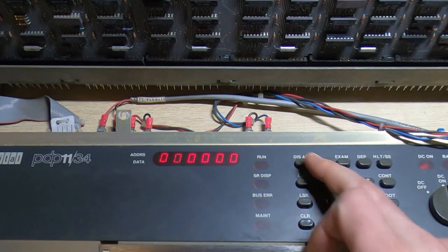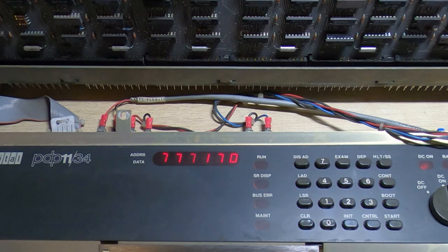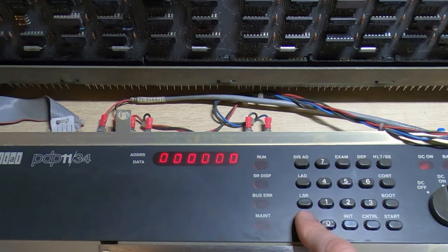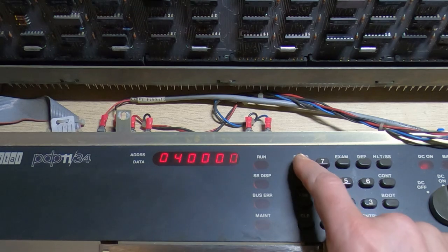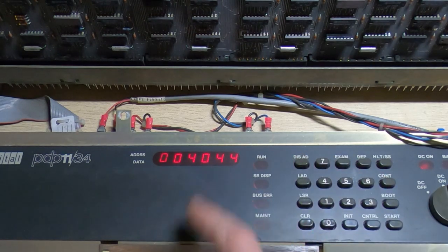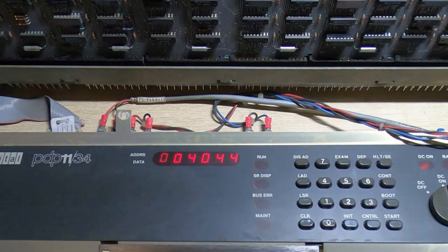So first thing is make sure we've got the address of the first register, so 777170 is correct, and we'll send a reset command, so we set the reset bit. Okay, and if we read back the same address, notice the values change. As I said, the state machine will tend to present different registers depending on where you are in the state machine.